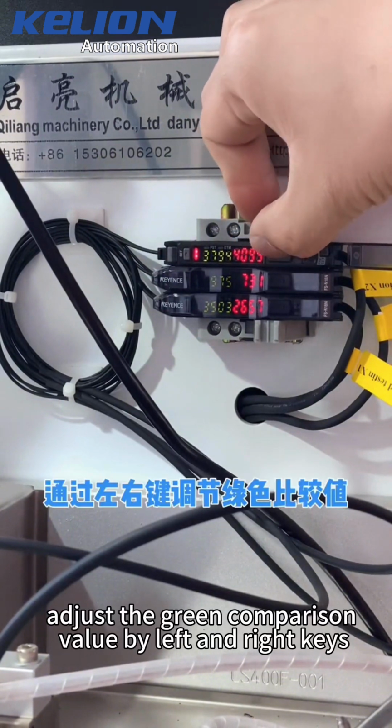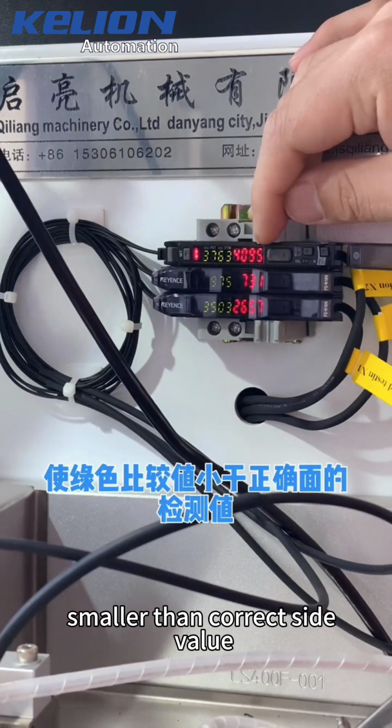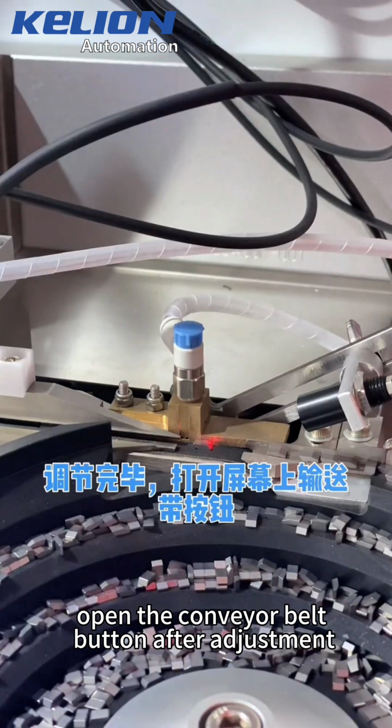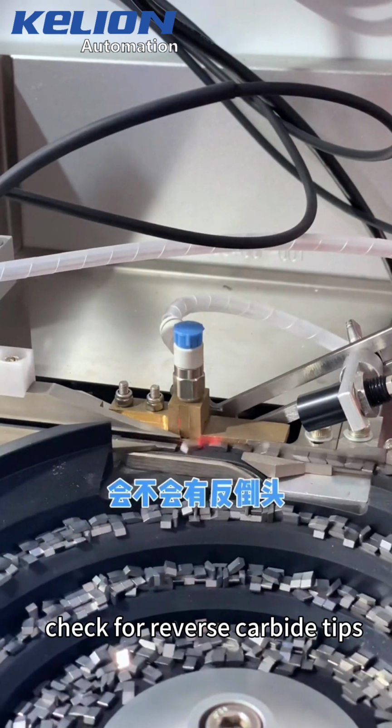Adjust the green comparison value by the left and right keys. Make the green comparison value smaller than the correct side value and larger than the wrong sides' values. Open the conveyor belt button after adjustment. Look at the carbide tip selection. Check for reverse carbide tips.